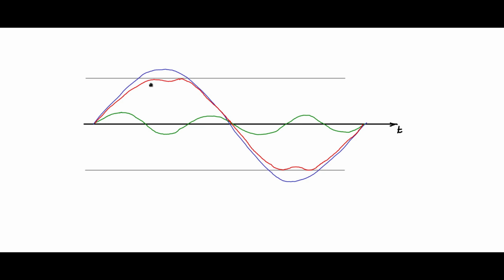Now this triplen compensated wave shape, the red one, if I use it as a modulating signal, then it contains within it a fundamental which is more than 100%, and therefore I am able to get more than 100% modulation if I inject triplen.